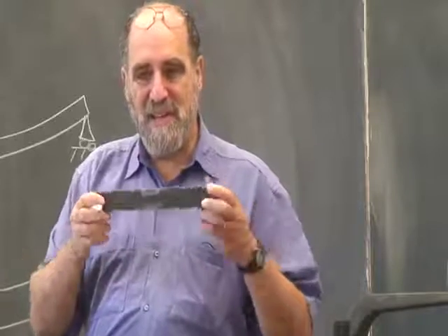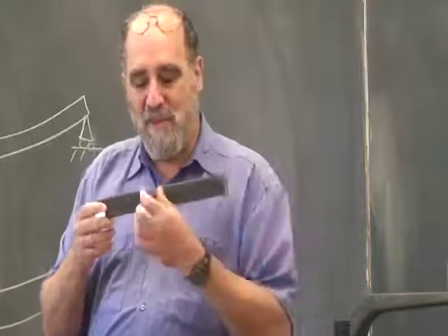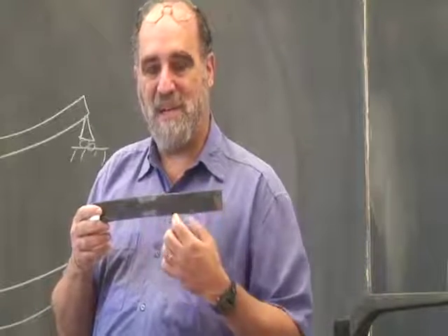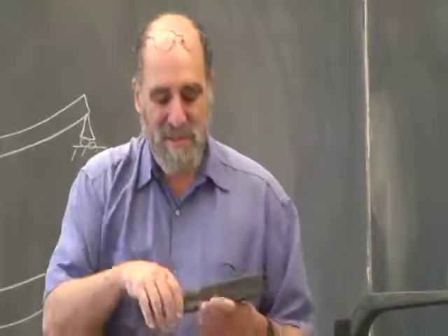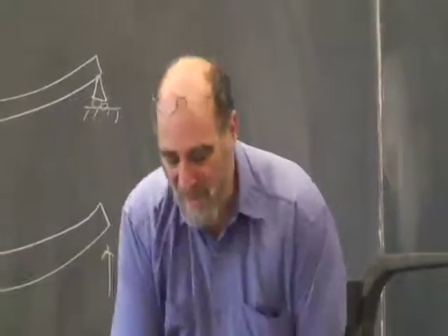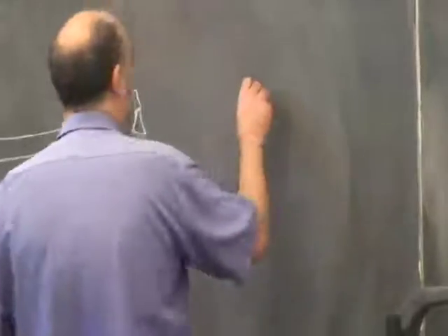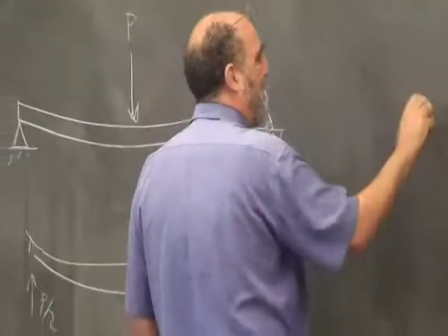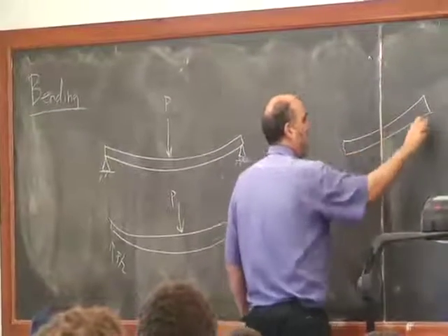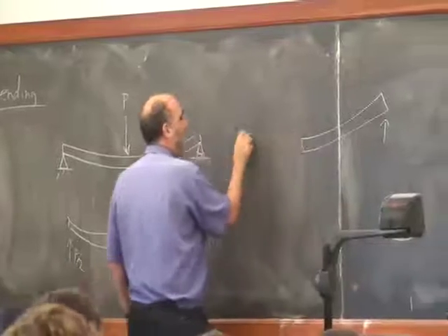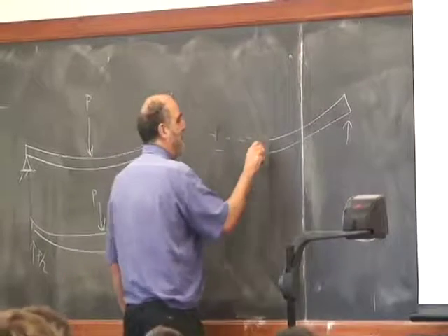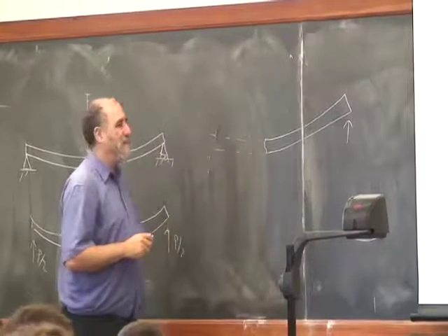Now, the nature of this bending is that we have this whole collection of tension and compression experiments in here, and we have a whole collection of it here and a whole collection of it here. But to start with, let's just look at one little section here and look at this bending experiment. So a way of conceptualizing this thing is to draw a free body diagram, say, of just the right part of this thing, which has this thing going up here. I've cut this away, so I draw it only with a dotted line, and there's little forces here, but I'm just drawing with dotted lines. And when I cut this, I have to fool it. This is this idea of a free body diagram.